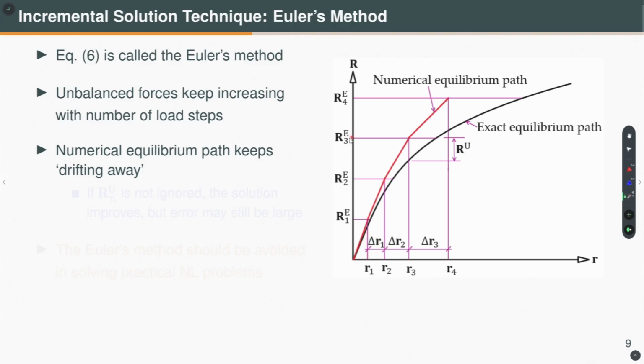I apply the next increment and use the tangent stiffness. So, this line is parallel to this, which is the tangent drawn at that point. This way, as you can see, I get the solution. For incrementally applied load, I am solving a linear problem in each load step. The force displacement relationship within a step is linear. I am solving a linearized problem for each load step.